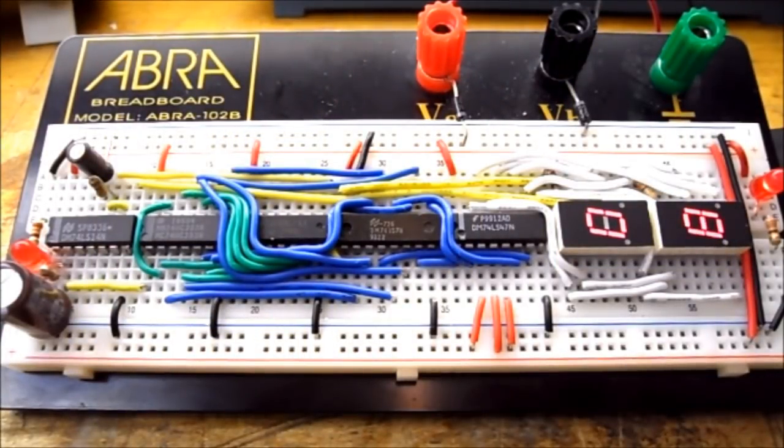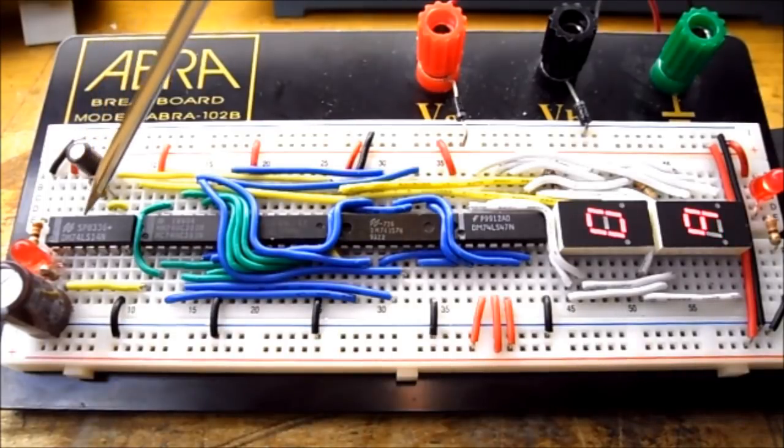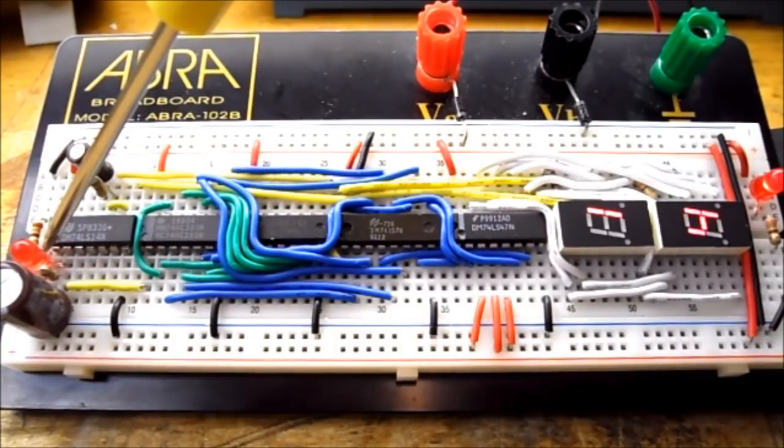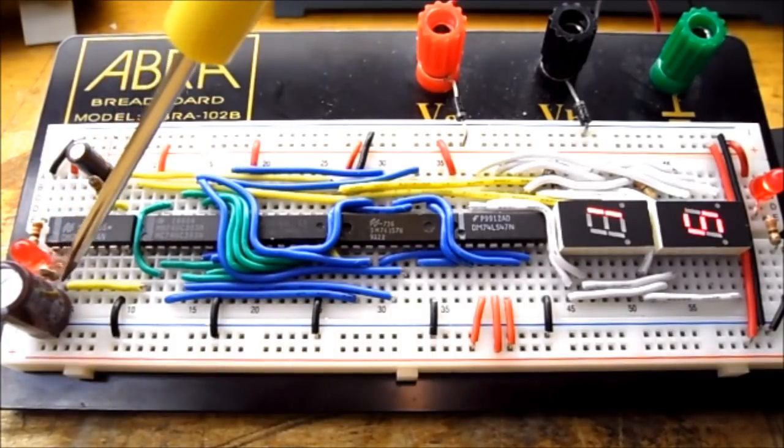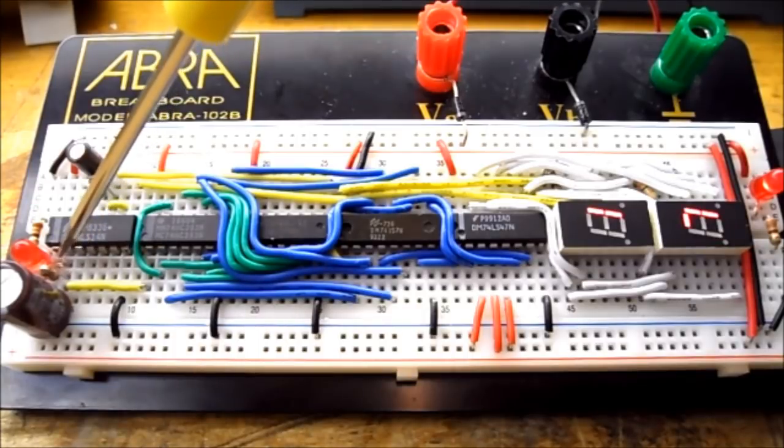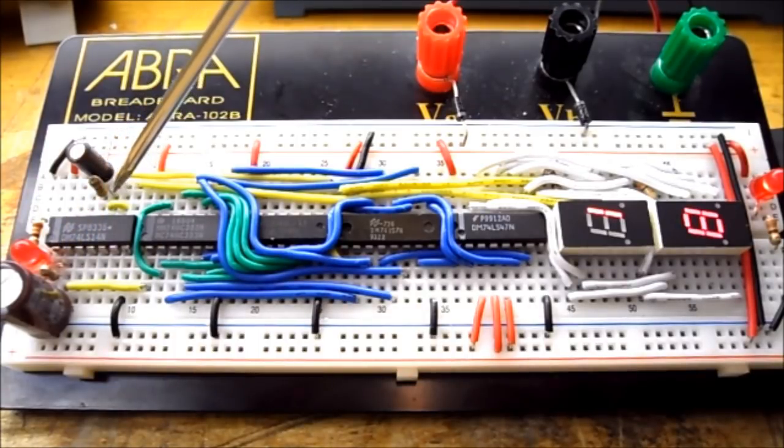So this is my completed circuit. At this end of my circuit I have the 7414. So you can see I have a slow clock hooked up at this side. So this is my 1 Hertz clock. On this side I have my fast clock, or 400 Hertz. Notice I didn't bother hooking up an LED to it because it would blink so fast I wouldn't see it blinking.